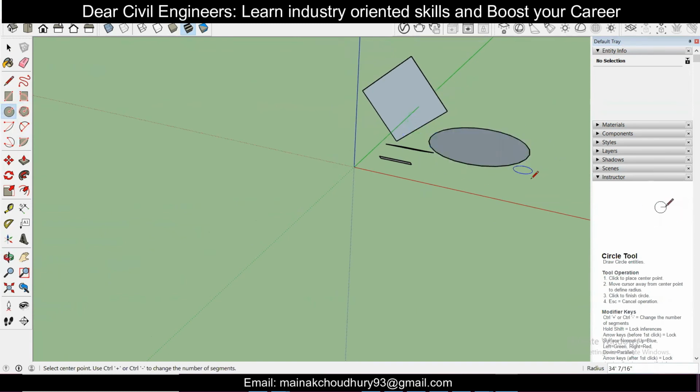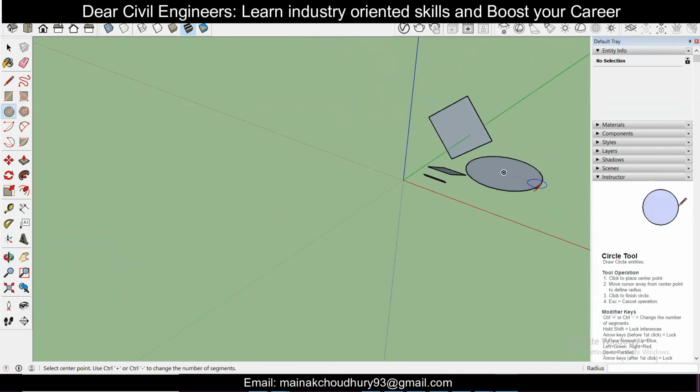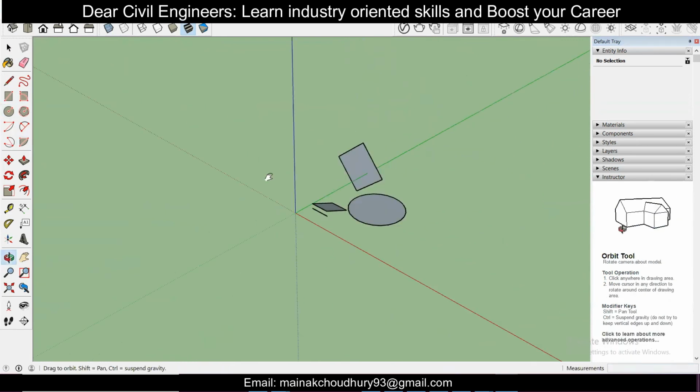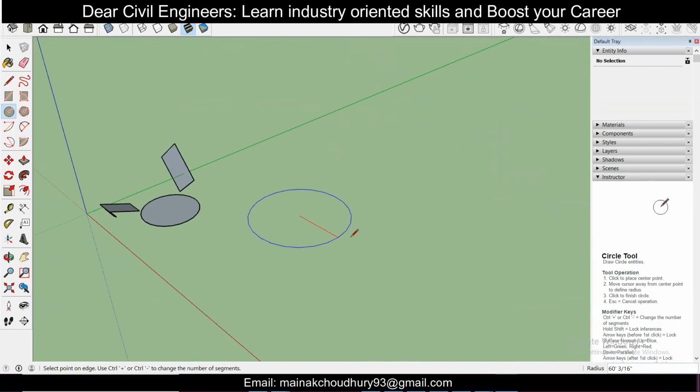For the circle, this is also pretty simple. You can just create a circle like this. If you want to insert the diameter of the particular circle here, what you need to do is single click on this, and the radius, suppose I give 100, and this circle will be created. And let me give 200. This circle will be created like this.